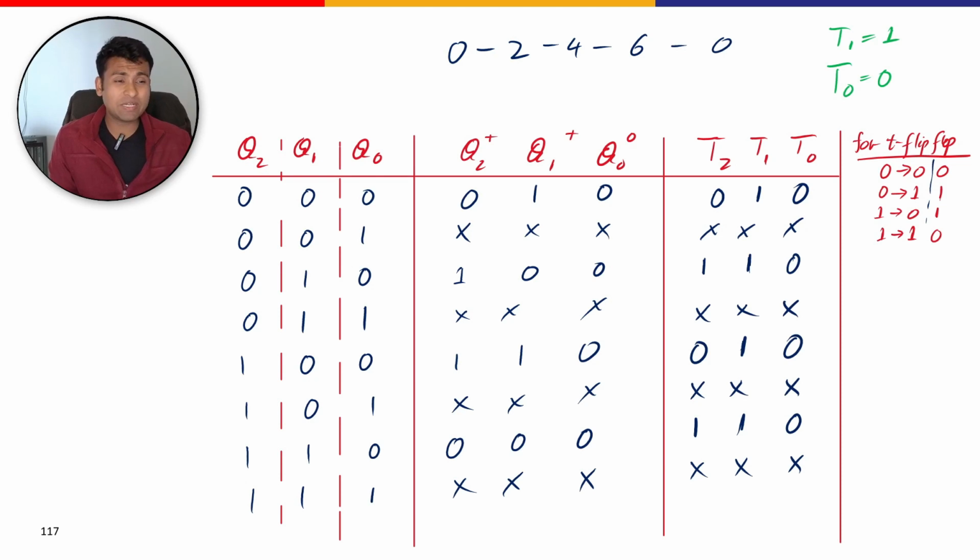I always recommend looking for patterns like 0001, which refers to an AND gate, so it must be an AND of some operation. If it's 0011, 0011, then it definitely means it's the second variable from your truth table. If patterns like 0110, 0110 are coming, then it suggests something like an XOR gate. So you need to keep an eye open for which two variables can be clubbed together, and most of the time it falls into a usual simple expression.